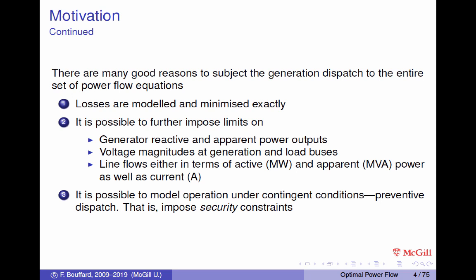So there are several good reasons why we want to have a full description of the set of power flow equations. First, we want a more accurate representation of losses so that we can minimize them as much as we can. And we also want to be able to impose limits on generator reactive and apparent power outputs.